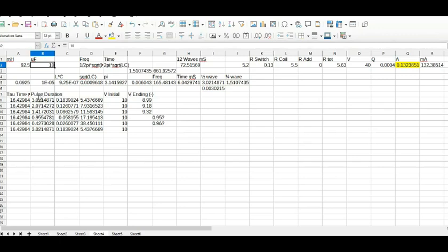We also know the pulse duration that we're hitting the coil with the cap. Now when I look at the spreadsheet, I see I made a mistake, because I'm saying that the spreadsheet is half wave. Half wave is where the cap goes most negative. The actual pulse duration is quarter wave. That's when the cap discharges fully. But it doesn't matter.